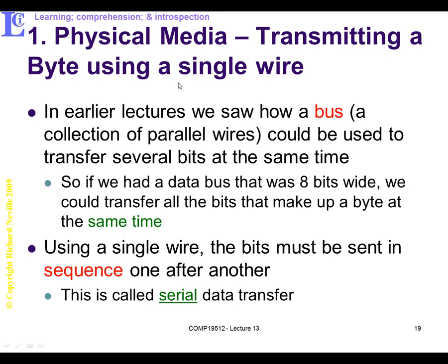So what we've seen now is we cannot, and it would be far too expensive to have 8-bit buses going out from your house. Instead of one single cable coming out, you need 8 to represent 8-bit words. So you couldn't do that. So buses over long distances are not possible. Over short distances on silicon or on motherboards, it's quite easy to have 8, 16, 32, 64 or even more bit buses of parallel wires to transfer bit parallel information. Normally this was done 8 bits wide, and these were transmitted 8 bits at the same time down an 8-bit bus or a 16-bit bus. This can't be done over larger distances, so we need to use a single wire.